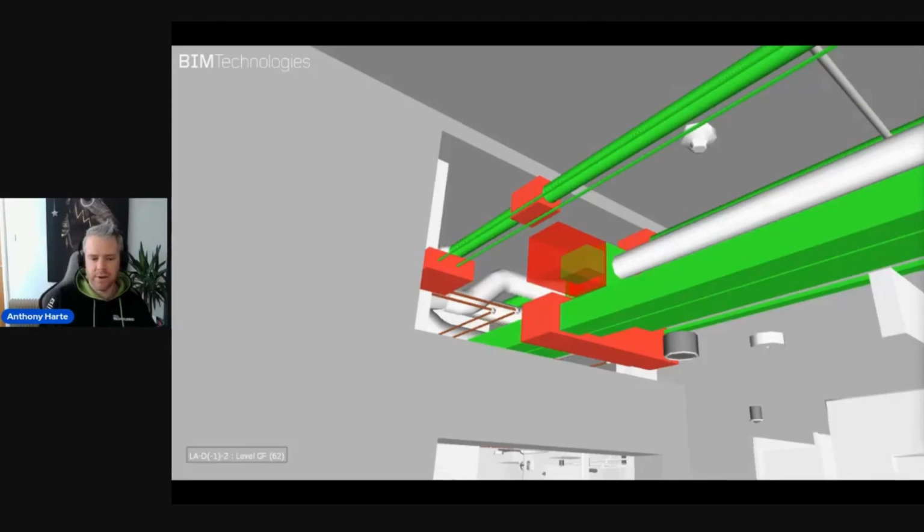So things like fireproofing and fire stopping and fire rating of objects has become a real big topic, and how we can incorporate those requirements into BIM deliverables. So we are seeing more of this within the UK here now. Again, it's a managed process, so I would audit these objects as well, make sure they're in there, make sure they've got the right data attached to them, and those would be at set stages of the project.